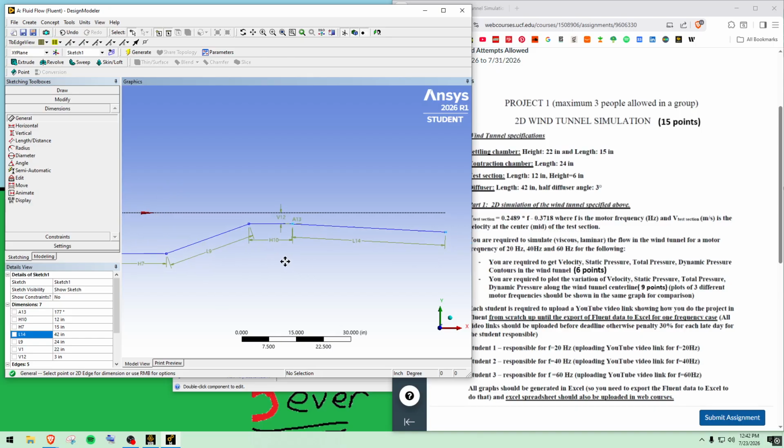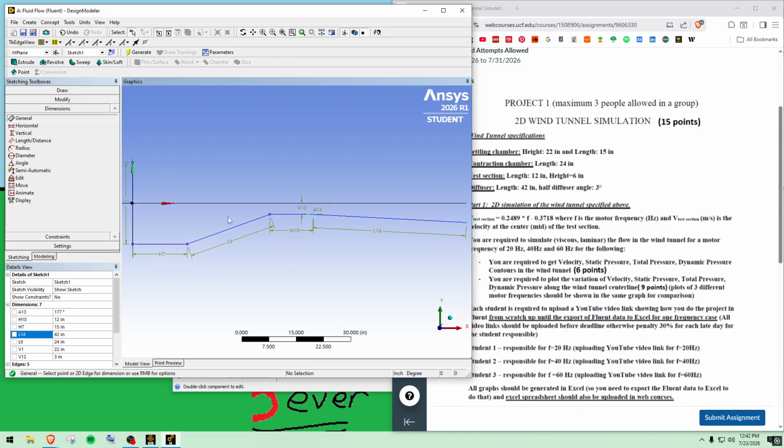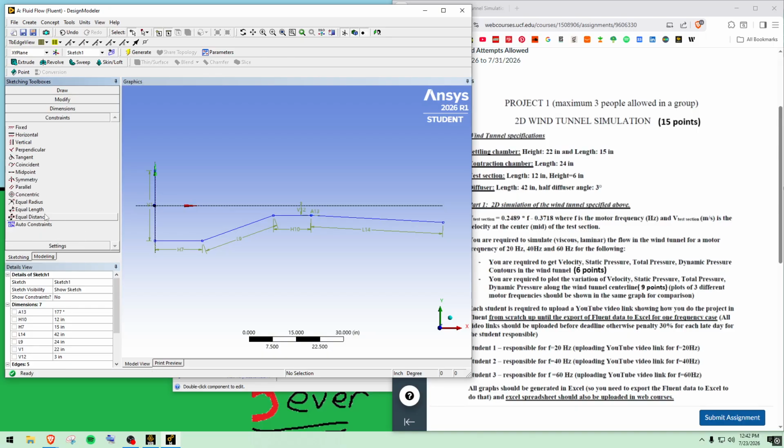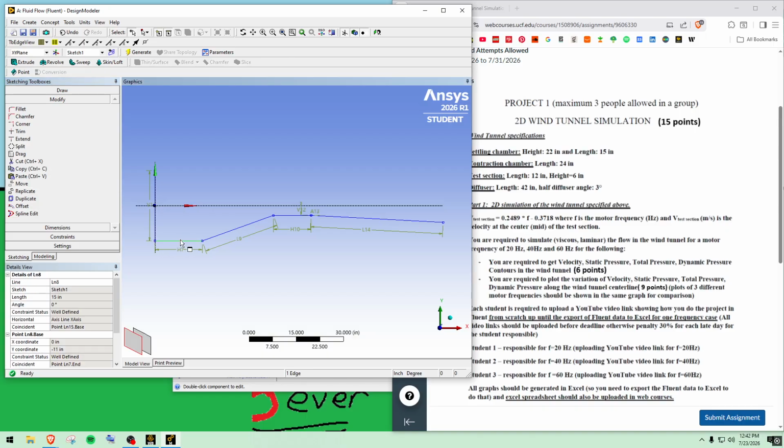Alright, obviously we want the other half right here. So we're going to go into modify, and then we can hit replicate. Actually, I'm going to select my points first, then hit replicate. I'm going to change R to 180. Then we can click our anchor point. You see I have our little thing floating around.